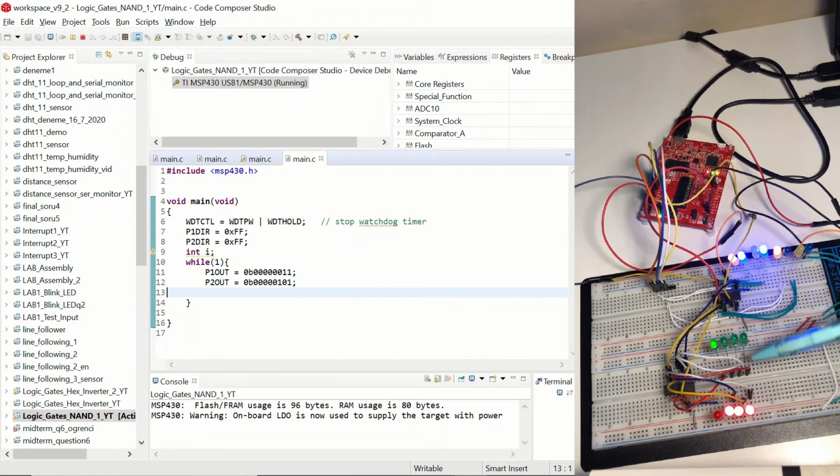And you can see that on the inverted side, we can see 0, 0, 0, and 1. Actually, this output is the output of an AND gate, because for 0, 0, it's 0, 0, 1, it's 0, 1, 0, 0, and 1, 1, the output is 1.